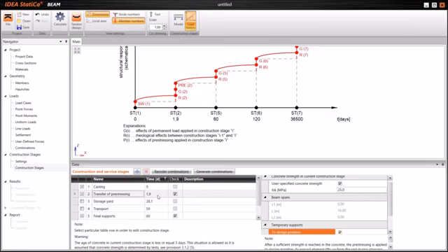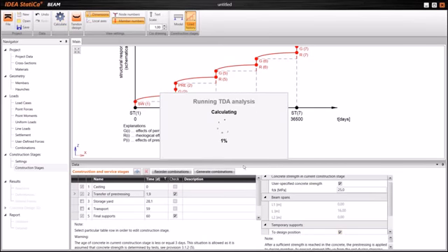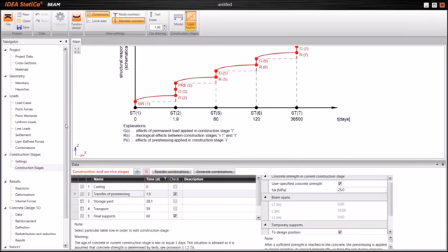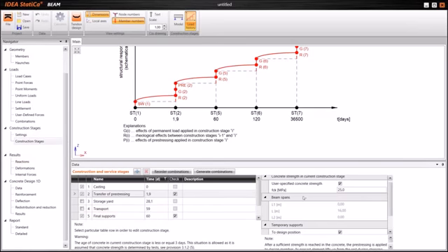If we have some heating of concrete, of course it is less, but we work with equivalent time. Of course we lost the data, so then we have to recalculate it. By the way, if you input this 1.9 days as the age of the concrete, then it is not allowed by Eurocode unless you also check, really test, the concrete strength. So the program would not allow this case if you do not specify this value.